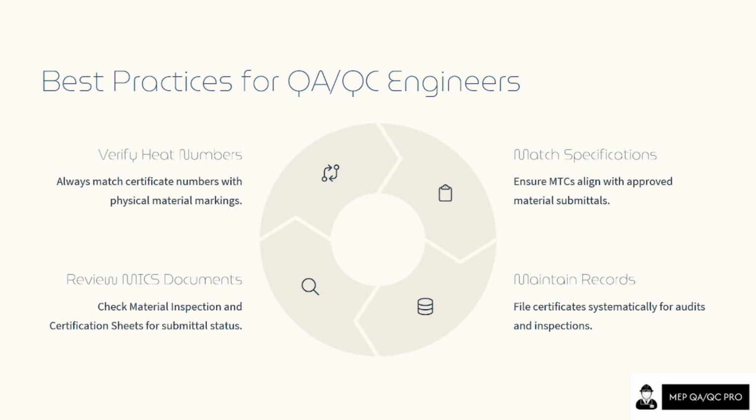I hope this is clear to everyone, because nowadays the client or consultant is looking for the material test certificate against the material delivered at site. So whenever you are raising an MIR inspection, please make sure you attach the material certificate.